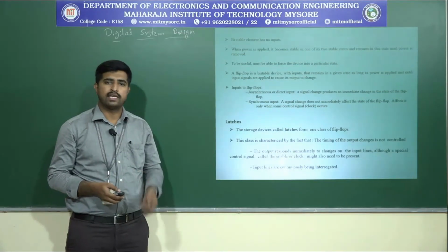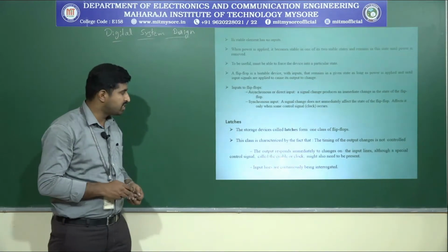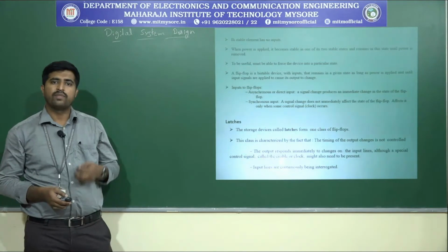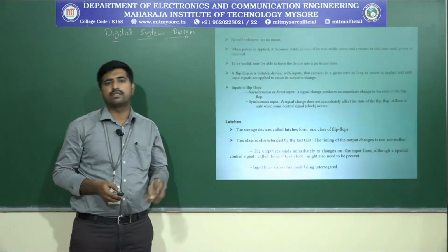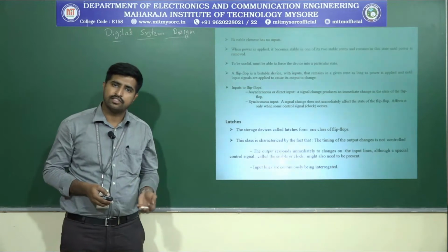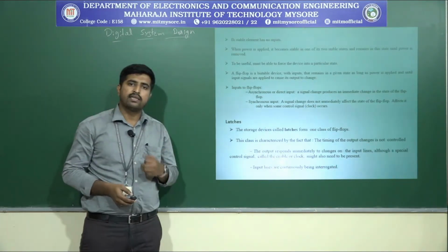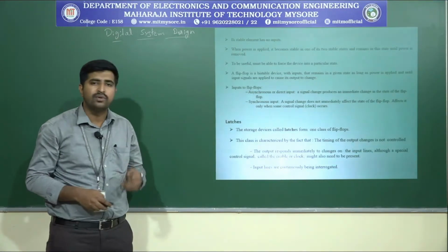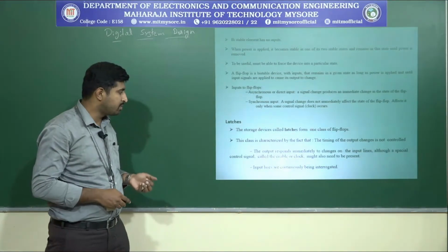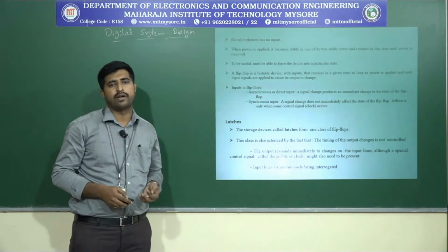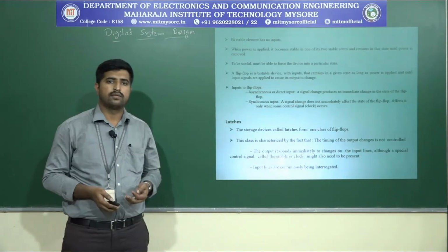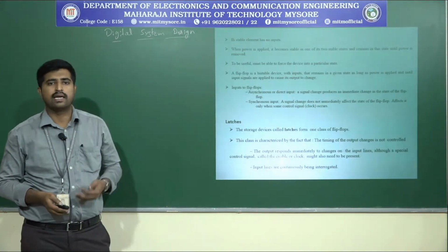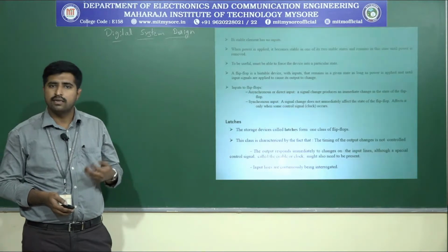Next we'll move to latches. Latches are also storage devices, and these latches are a class of flip-flops. The outputs of these latches change immediately as the input changes, and the latches interrogate the input lines continuously. That means we can say the input lines are continuously being interrogated. There are several latches available, based on the input lines and the enable lines, so let's see them one by one.